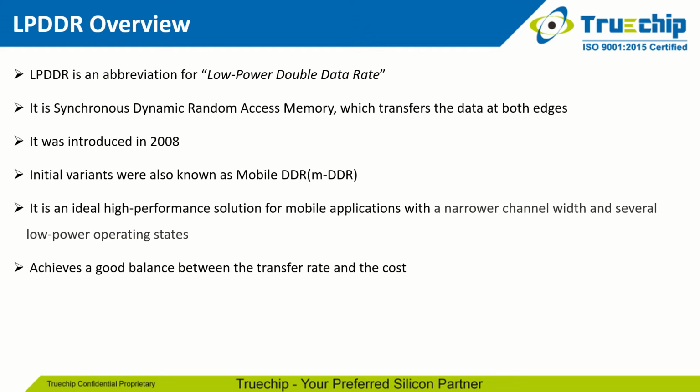LPDDR technology is developed independently of DDR standards in terms of performance, battery life, and data transfer rates. As it was targeted for mobile devices only, data transfer was clocked with a low frequency and low voltage in comparison to DDR RAMs, which makes battery life even more long lasting for mobile devices.